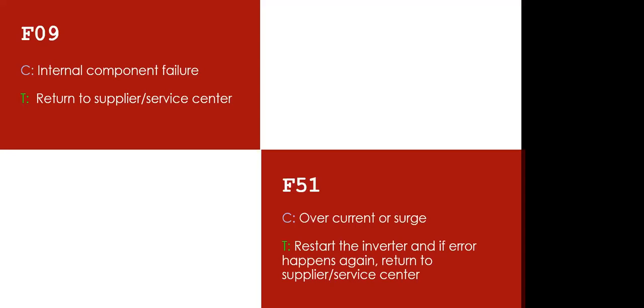It burns it. Another thing that can still burn is a particular capacitor on the main board, which is on the DC to DC converter side. So it burns all those components. If this happens, it really disappears when you restart the inverter, because before the F09 can occur on the system, definitely something critical has gone wrong on the site, either the surge, over voltage, or short circuit. All those can still cause it.